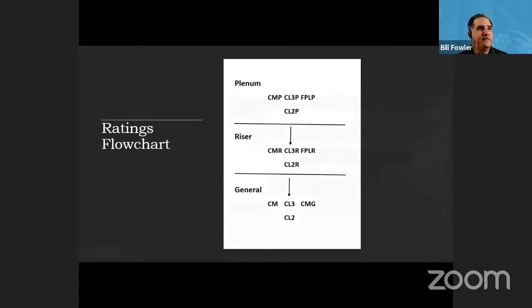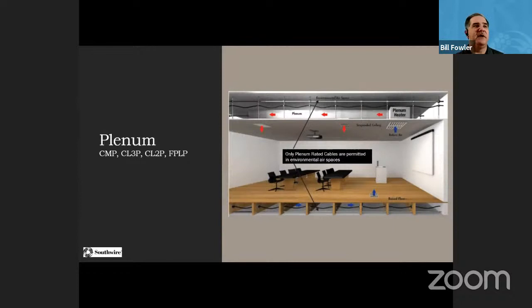So let's talk about actually the plenums. This is really a good picture to illustrate when we talk about plenums. We typically see a drop ceiling in a building here, and then you have the space that you're occupying in the building. You also have a raised floor down there in the bottom. And typically a raised floor has vents that have the conditioned air that will blow up into the space. A lot of times they'll use that for the HVAC ductwork because it's enclosed space and it can be used to force air into a space. Especially computer rooms, you'll see that used quite a bit.